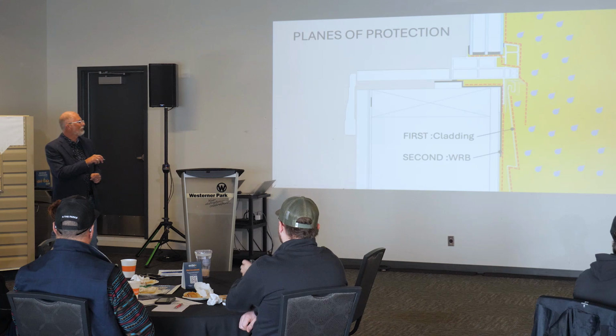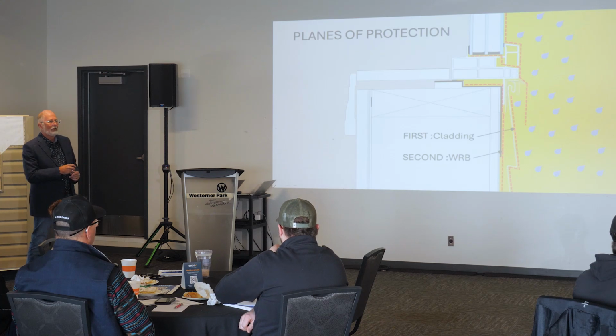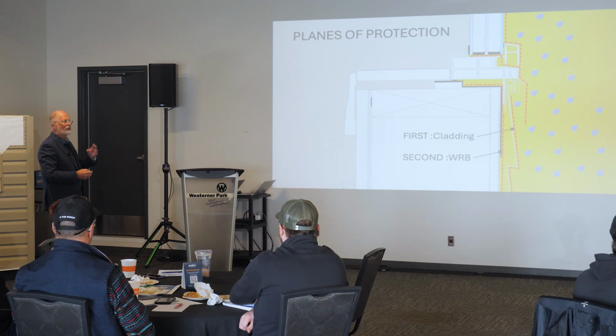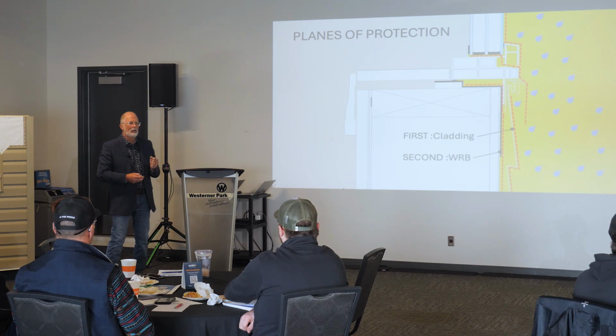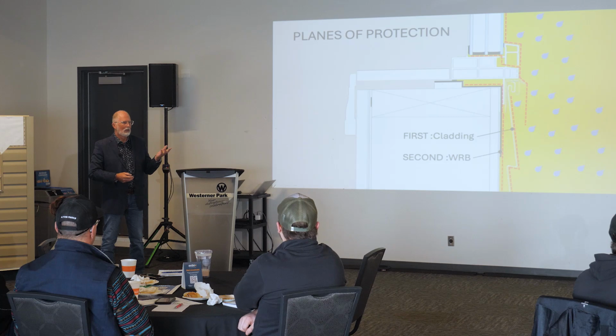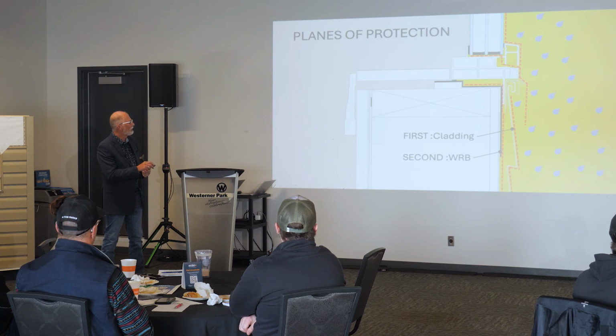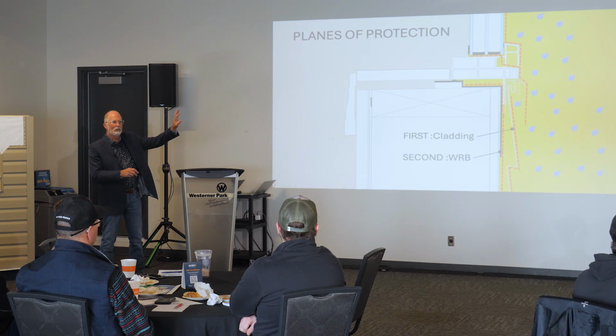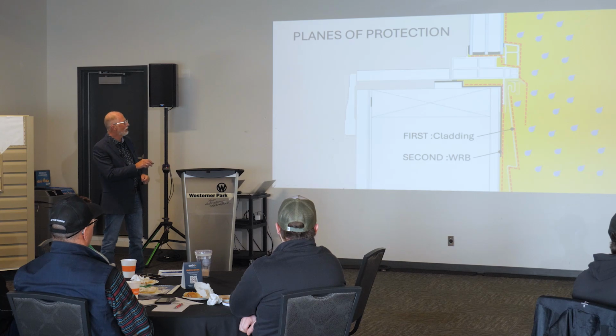What about the risk of condensation in that cavity? What causes condensation? It should be an exterior air environment, if you've got your air barrier down. So what's the humidity level here versus out here? Pretend it's not raining, it's winter time, whatever time of year. If it's dry, let's say it's 40% humidity outside, it's probably going to be 40% in there.